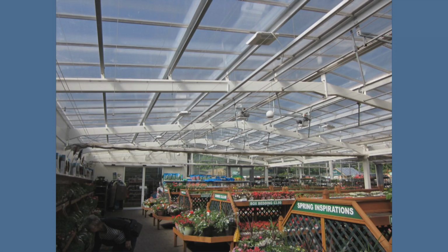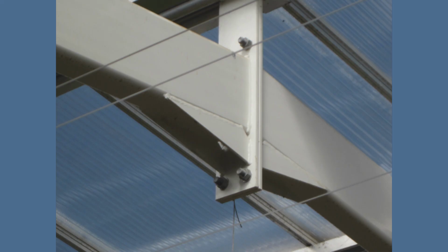And this is another one, same place, but a different part of the building. And again, if you look at the connection at the top there, this one's only got 2 bolts in it. It really is important that you have the right bolts. The structural fixings are the weakest link in that structure.